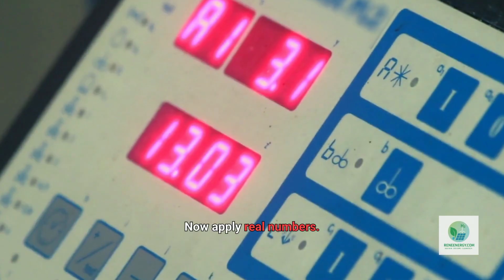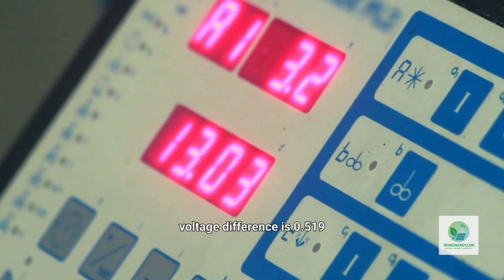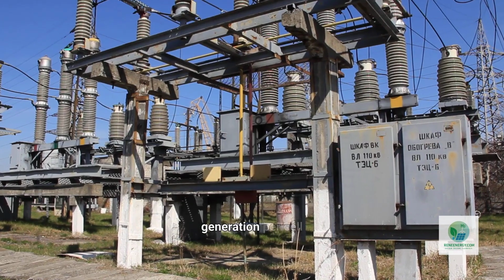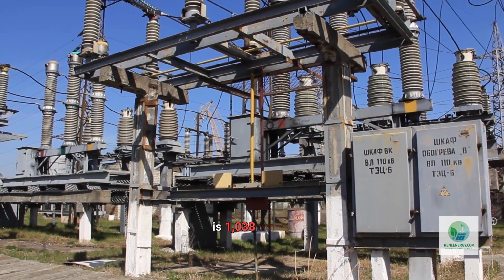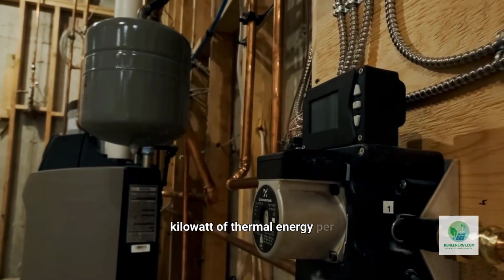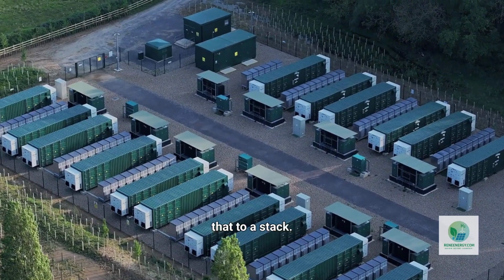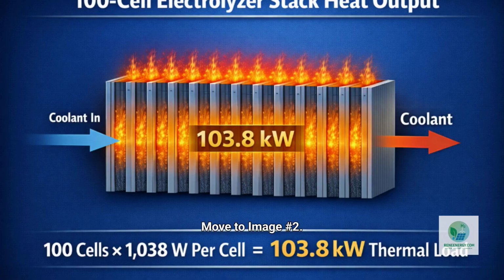Now apply real numbers. If the current is 2,000 amperes and the voltage difference is 0.519 volts, the heat generation per cell is 1,038 watts. That is just over 1 kilowatt of thermal energy per cell. And that is not a transient load, it is continuous. Now scale that to a stack. Move to image number 2.